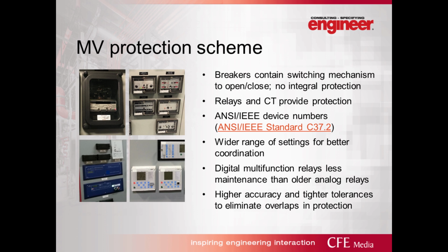So I'm going to talk a little bit about the differences between low voltage and medium voltage equipment. And I think the major piece that's different is the protection scheme. Unlike low voltage, the medium voltage breaker contains only the switching mechanism to open and close the breaker. It doesn't have any integral protection built in. That protection is really provided by separate relays and CTs.